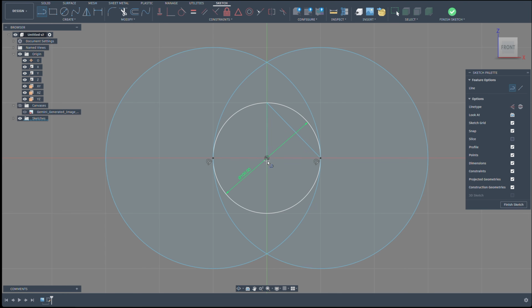From this same point, through the previous point, we will draw a line ending at the boundary of the large circle. Now, draw a circle from the top point of the base circle to the previously found point, with a radius equal to the distance between them. We have obtained our second tangent point.